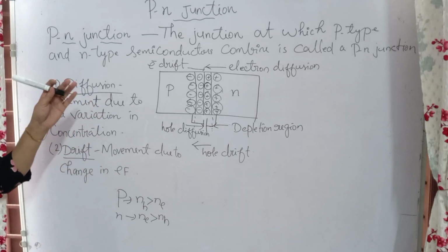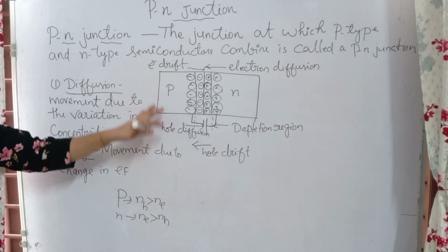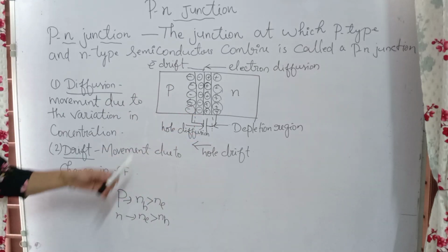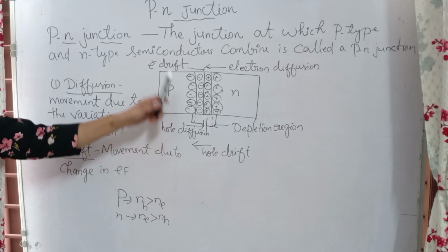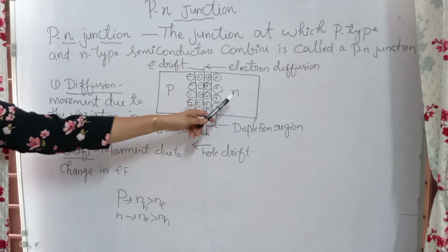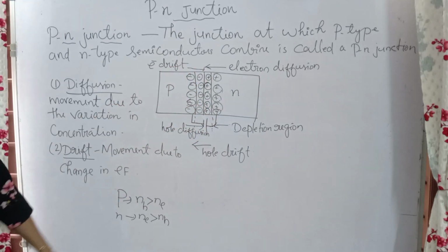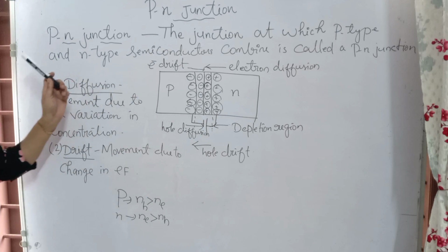So you have to just understand the concept, how it is flowing, what is happening inside a PN junction. Right. So the first thing that you have to remember is, in the P region the majority charge carriers are holes, and in the N region the majority charge carriers are electrons, and diffusion is happening due to these majority charge carriers, right?